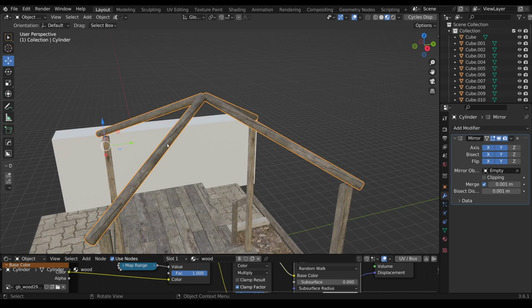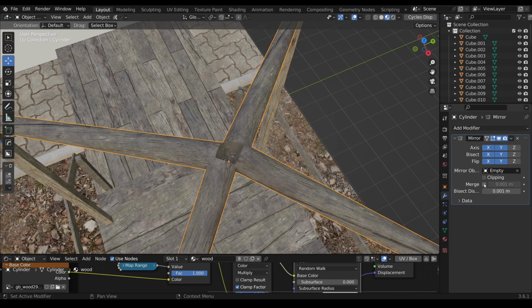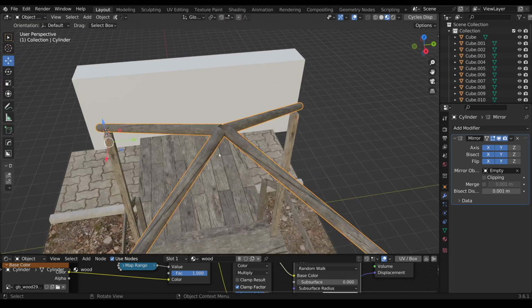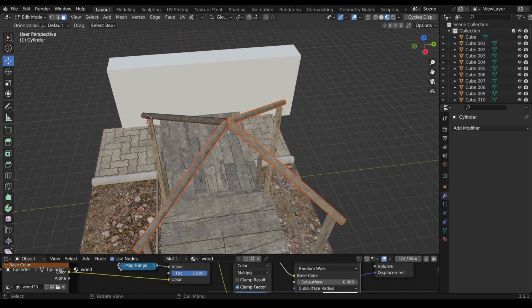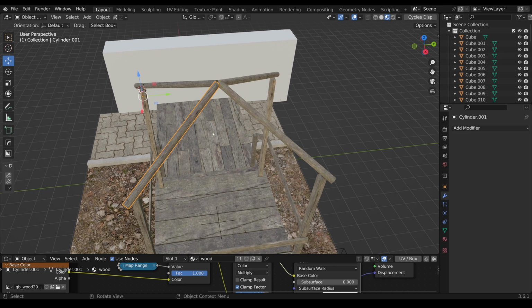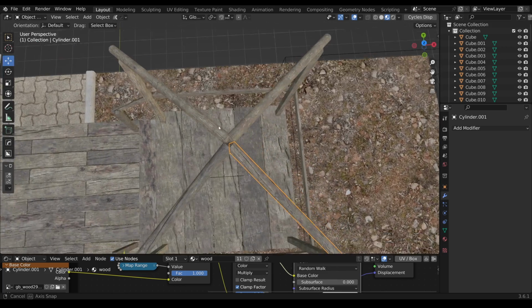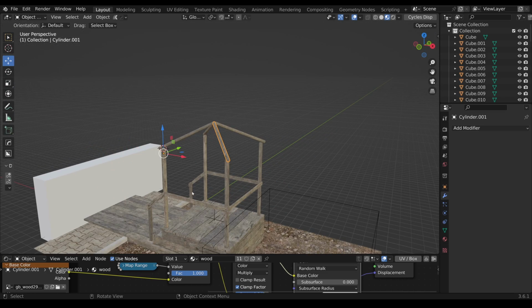We could apply the mirror modifier, but we need to do a small tweak because the object will be merged. Go to Merge and deactivate it, go back in, and make sure it's independent. Then exit to Object Mode, apply the modifier, and go back in. Select All, press P for Separate by Loose Parts. Now, separate objects have been created, each with a completely different texture and brightness level. It looks great. I'm considering brightening it up later. It seems a bit dark. You can always decide that separately for rendering.